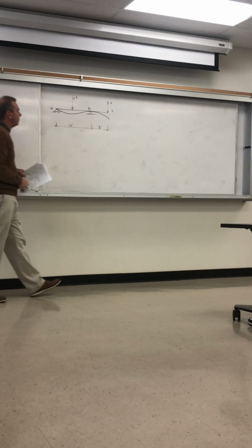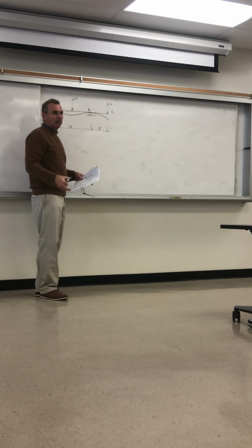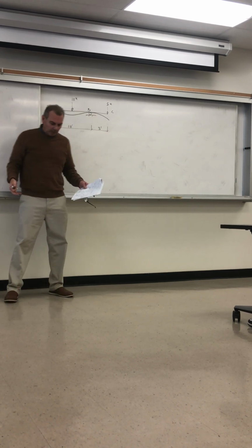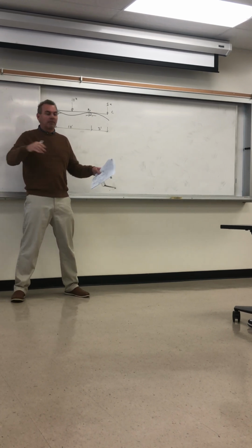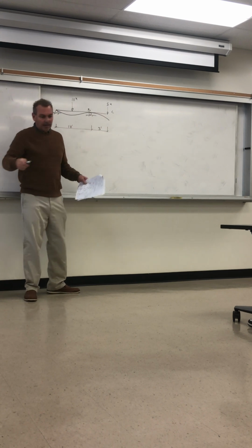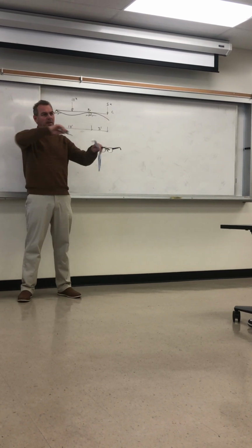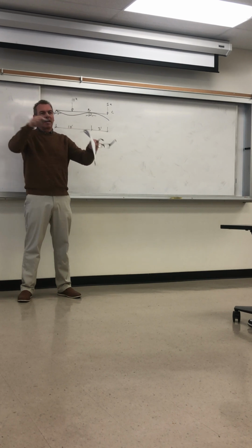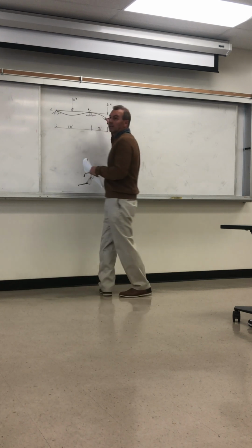Okay. So it's kind of like if you put a board over a single brick and you stood on it with one foot on either side like that, okay? And it would deflect. If you just think of this part of it, you put your foot on one side, you put your foot on the other, so it's balanced, the moment. Across the bed, it's bending like that. If it's bending, if it has curvature, it's got moment in it. So it's got bending moment as it's coming across here.